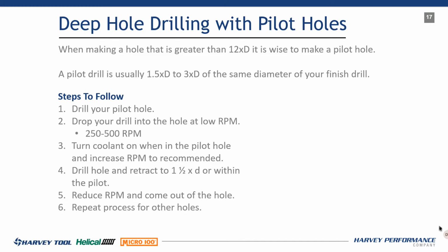Number one is deep hole drills are probably going to have coolant through. They should have coolant through. It's going to give you the best results. And remember, if they don't have coolant through, think about pecking. Okay, very important. First thing you're going to do is drill your pilot hole.